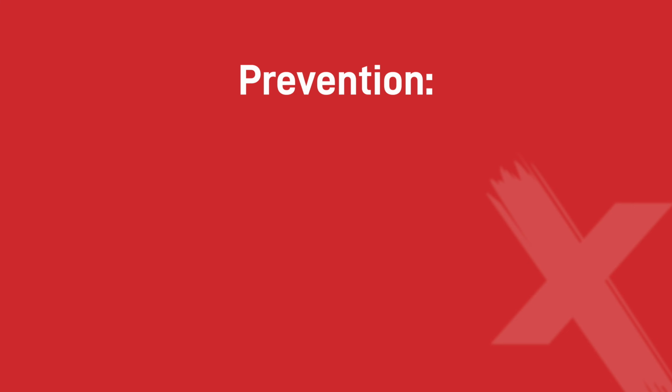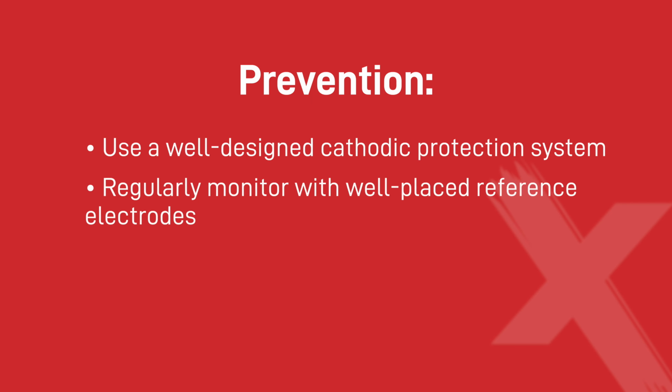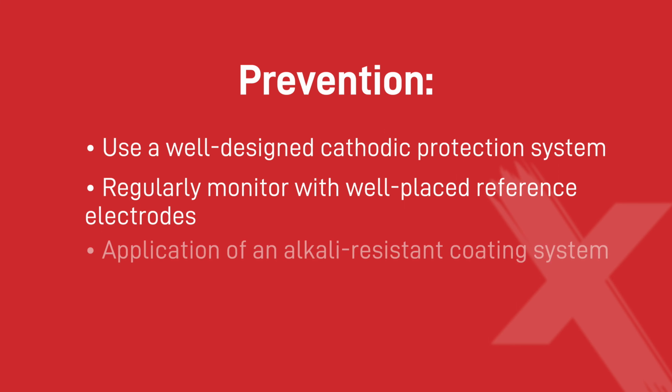To prevent this issue, use a well-designed cathodic protection system, regularly monitored with well-placed reference electrodes. An application of an alkali-resistant coating system will solve any future occurrence.